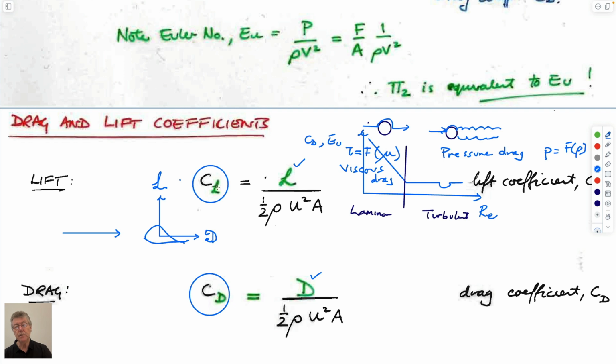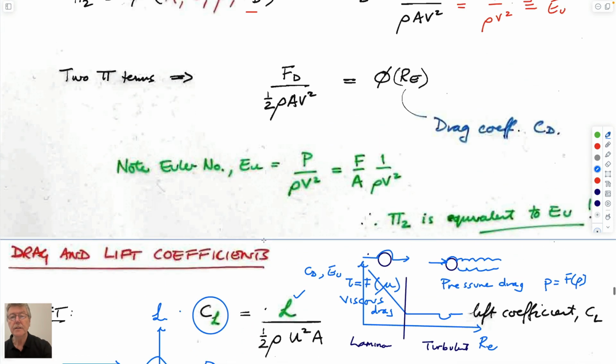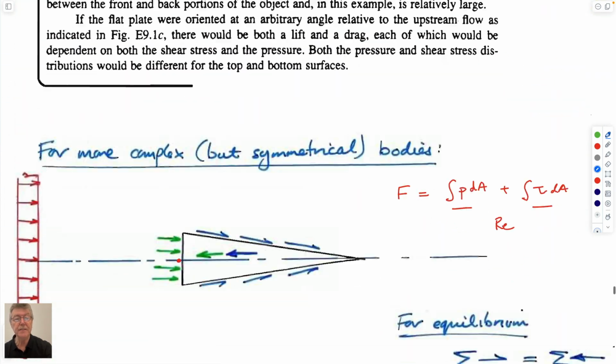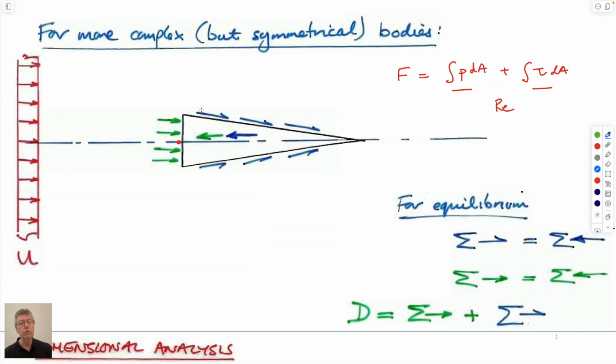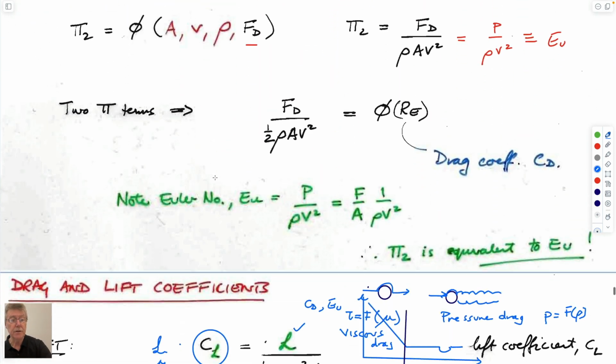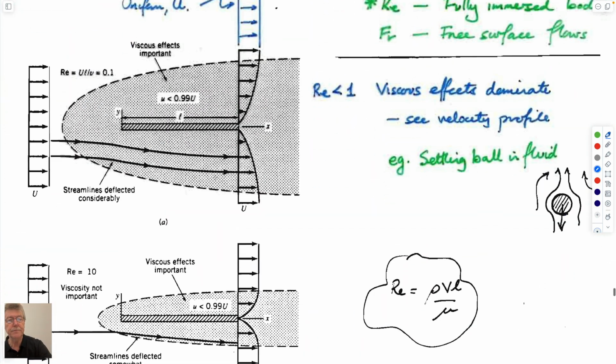If we know what the drag coefficient is, we can always calculate the forces that are applied. And depending on the problem we're solving, if we know the weight of the particle and its geometry, then we can solve for the velocity. If we measure the velocity and want to calculate the dimensions of the particle, then we can solve for that as well, either way. That, I suppose, is a manifestation of this picture, right? We'll always have pressure drag, we'll always have viscous drag, but the magnitudes of their proportion will vary based on the flow regime. And I think that's what is illustrated in these figures.